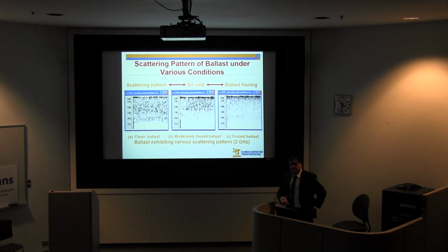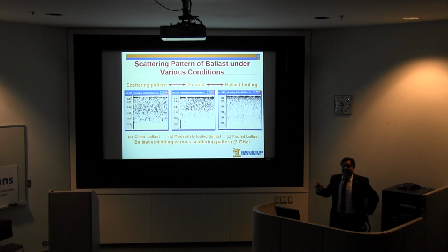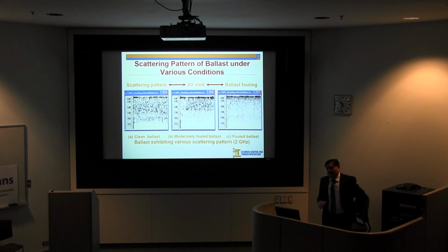There are a lot of retaining structures, water retaining structures, where you need to do a lot of non-destructive analysis, where there are a lot of cracks and all that. So the possibility of water coming out of the retaining structure. So can this, or probably something similar to this, be used? If there is a little crack in the structure that seeps a little water, I would use myself an impact echo or ultrasonic and so on. That will be a little more effective because it's also localized. It's definitely going to work much better than GPR.